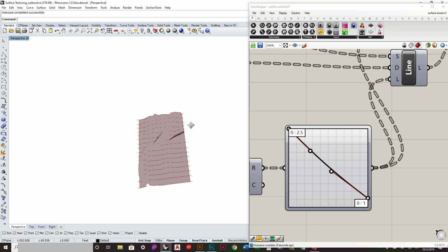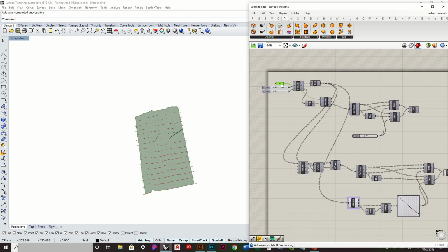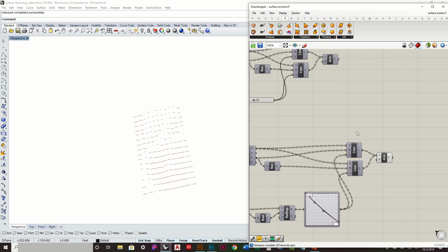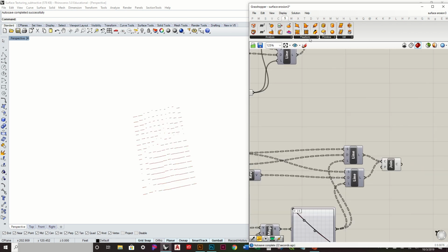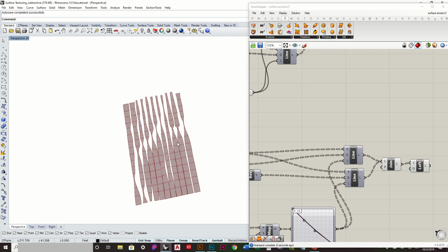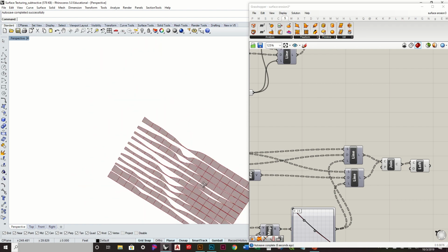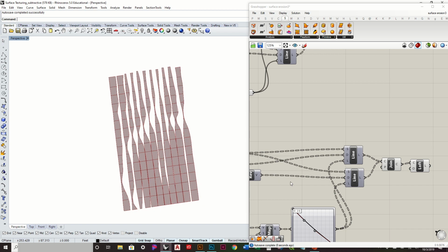And let's try, and let's actually, instead of just looking at curves, now I can go to surface, and let's turn off my original. And let's go ahead and loft these. Alright, so now, based off of those kind of ridges, we start to see how it gets kind of thin.